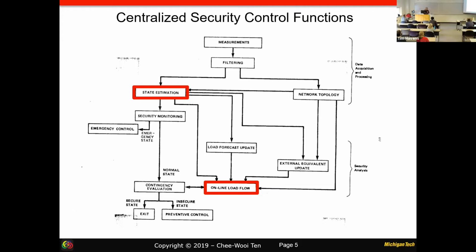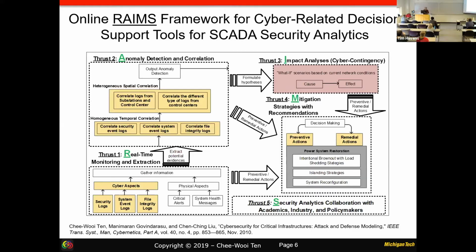This is a much more sophisticated network, but basically this is, again, a centralized framework that gets the data from state estimation. And then we have this online load flow analysis, which I highlighted in the two major red boxes, indicating the telemetry meter data coming from hundreds of substations. I'm speaking about one transmission utility that could have maybe 300 substations they are monitoring under their territory.